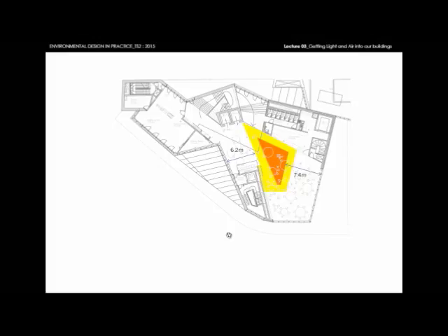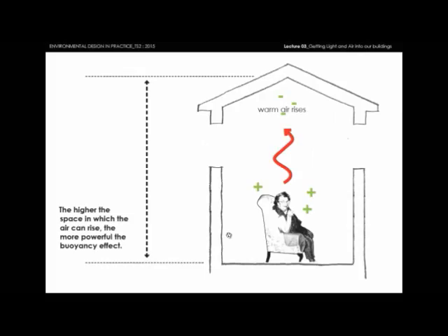And that relationship was to do with the depth of the space, shown here in plan, and the height of the space, which, as I say, became a metre higher as a function of a design change. And when that metre was added, it meant that the area which we potentially would have had difficulty naturally ventilating reduced substantially. So there's a strong relationship between that height and that depth.